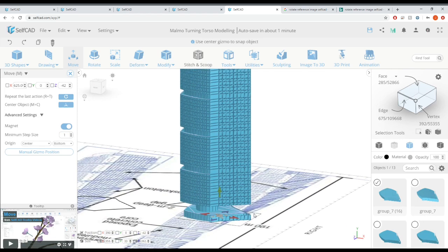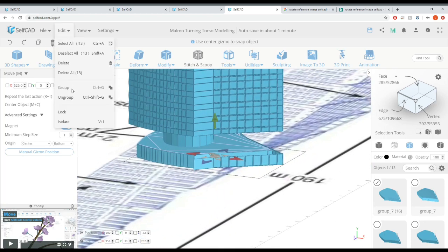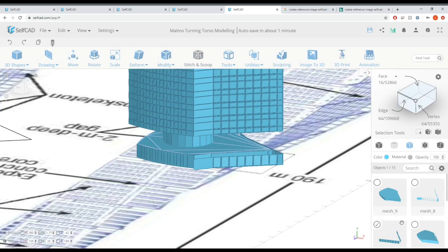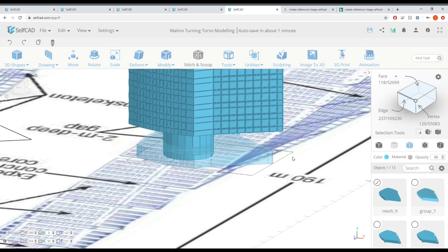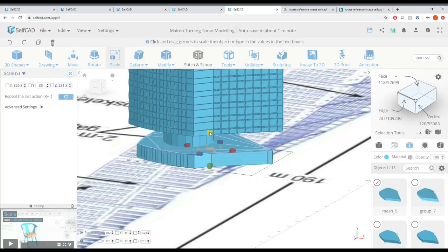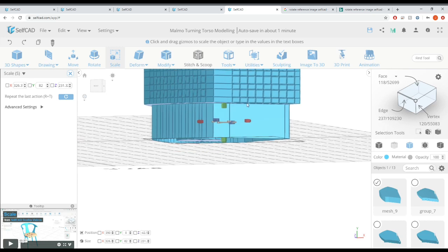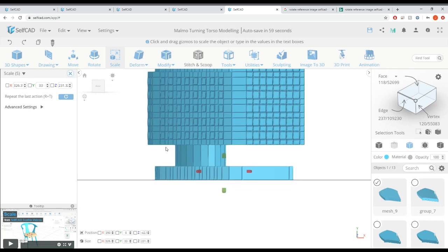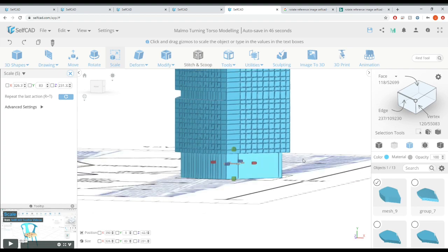So up to now, our building has been sort of floating. We're going to create an entrance lobby. So I've just copied down one of our sections, and we're just going to delete this glass portion of it because we just don't need it. And we're just going to now rescale it so it meets the underside of the first portion right above the entrance lobby.